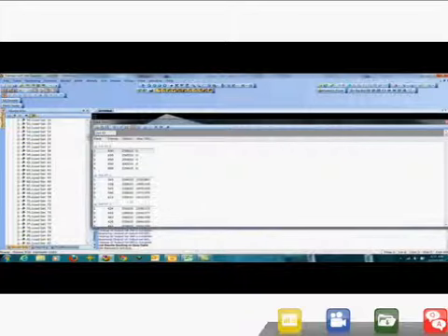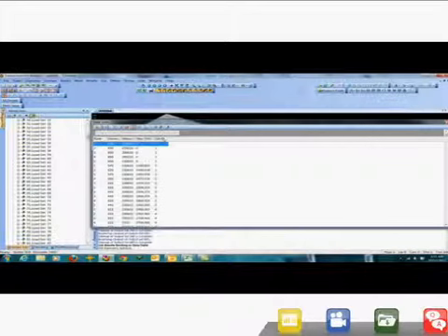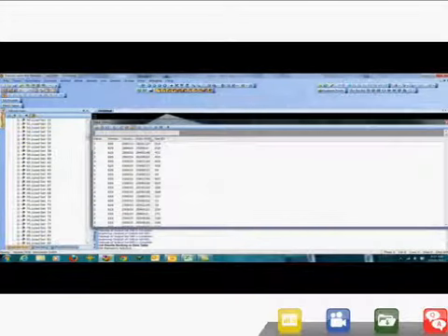So here's my data by set ID right now. It's subdivided as we told it to. But within each set now, I'm getting my top 5 von Mises stresses. I could just pop this over to Excel with a copy. Or also a neat thing we can do here is let's just bring this back in, and now it's not even subdivided by set. I can now just go right up and down here and find my top von Mises stresses instantly for the entire thing and see that it's element 629 in this set ID, so for load set 418.